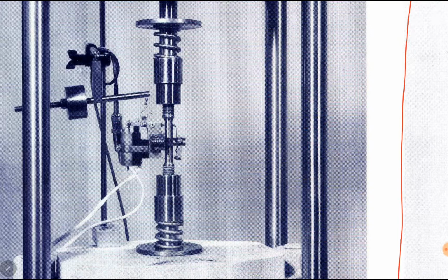Okay, at section 3, we can draw a free body diagram. This force P3. Summation of forces is equal to 0. So P3 minus 30, because P3 and 30 kilopounds are in opposite directions. So P3 becomes 30 into 10 power 3 pounds, or 30 kilopounds. Here are these 3 forces, P1, P2 and P3.